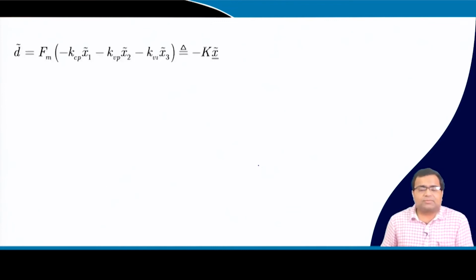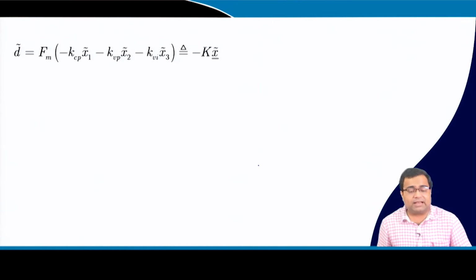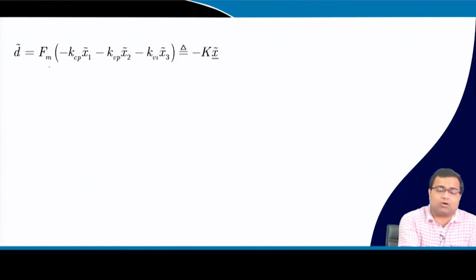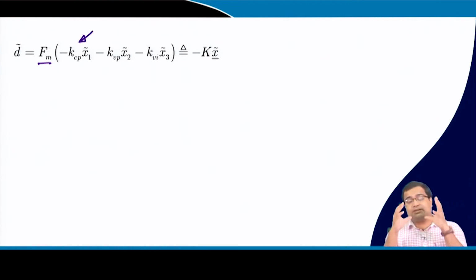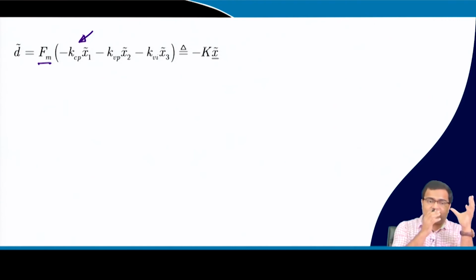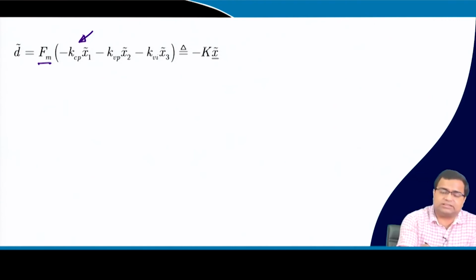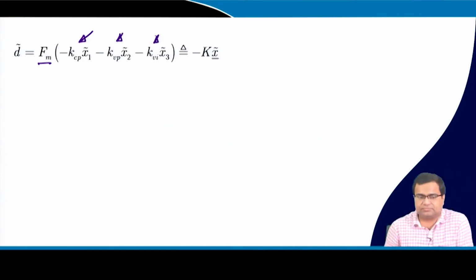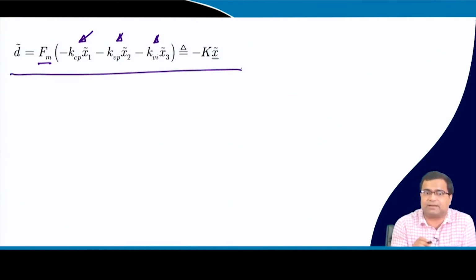Now if we take the duty ratio, it is the combination of the modulator gain. We are now taking the current loop gain Kc, because in current mode control we can also consider a current loop gain. This is the proportional gain of the voltage controller, and this is the integral gain of the voltage controller, and we can write it in state feedback form.